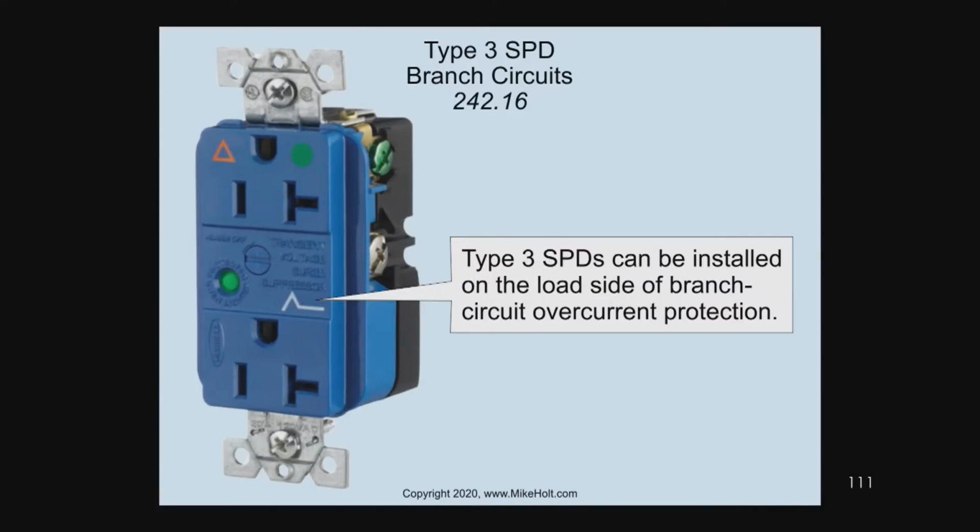Now the purpose of surge protection devices is to protect the equipment. But sometimes, and not sometimes, I mean, you have energy coming in as substantial numbers, and it's going to come in on the utility secondary conductors. It's going to come in on the wires, and it's going to go back on the same wires. John, explain why we have a type 1, 2, and 3. What's the reason? Can I just put a type 3 in there and just get a little strip and drop that in there? I'm trying to protect my expensive equipment, trying to avoid Murphy.